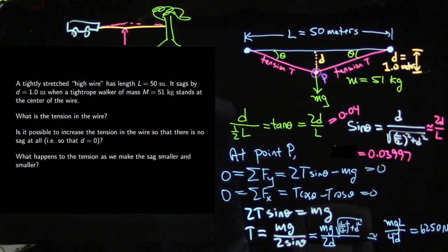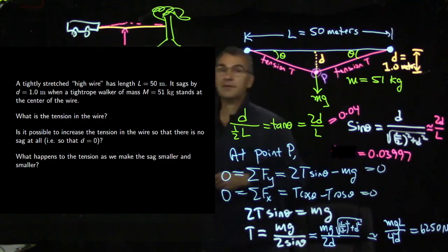Or maybe you could sit on the rope. So you could sit on the rope or you could push on the rope, but basically, if you apply the biggest force you can in the middle of the rope, it makes a really small angle. So then, the perpendicular force that you apply is multiplied by a big factor. That big factor is the reciprocal of the tangent of this tiny angle. So then the tension in the rope pulls on your car and might get your car out of the snow. I've never tried it. I look forward to trying it sometime.